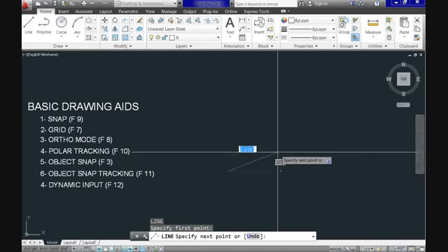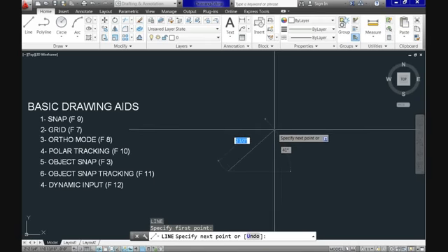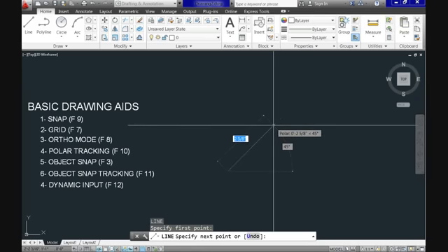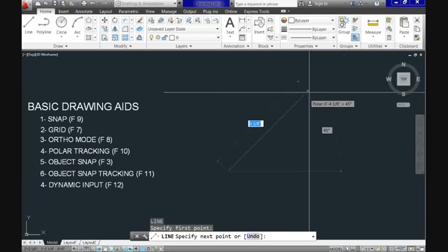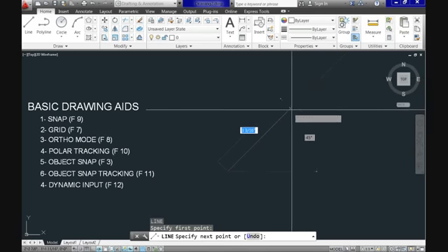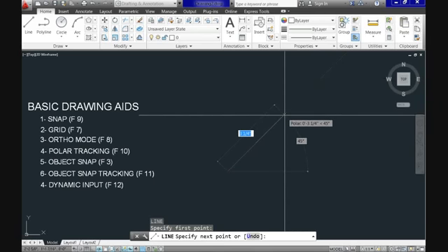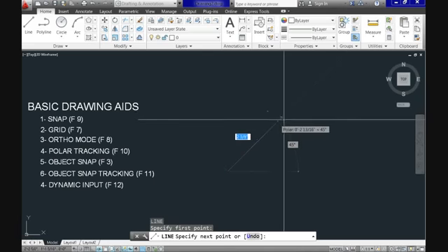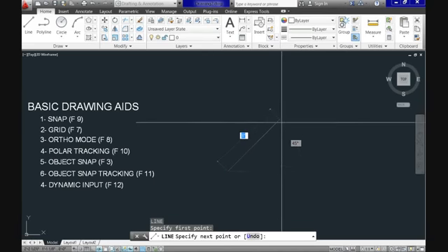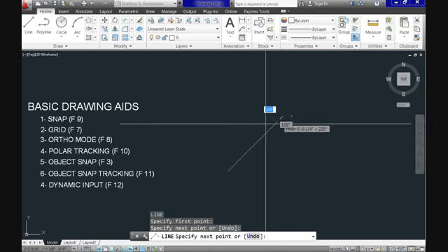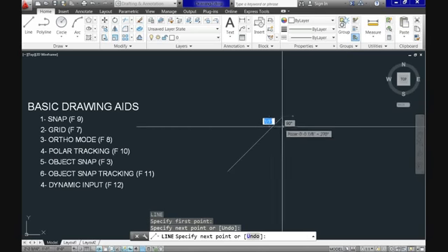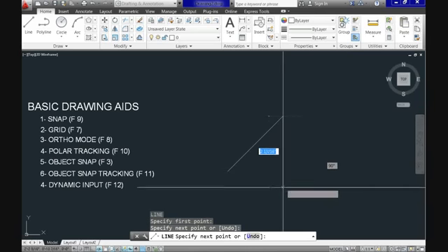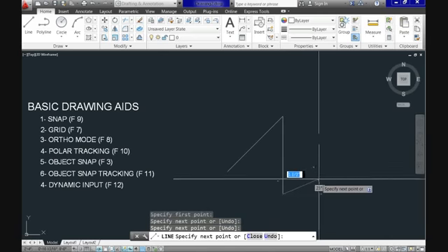We also have other options here, which you can see later on your own. When we click OK and repeat the command, you can see that when we get close to any angle near 45 degrees, it snaps at that angle. You can combine this feature with direct entry the same way we did with ortho mode, and it's a very efficient way to draw at specific angles without having to use polar coordinate entry.